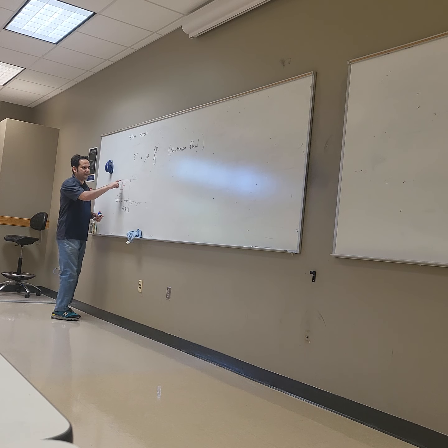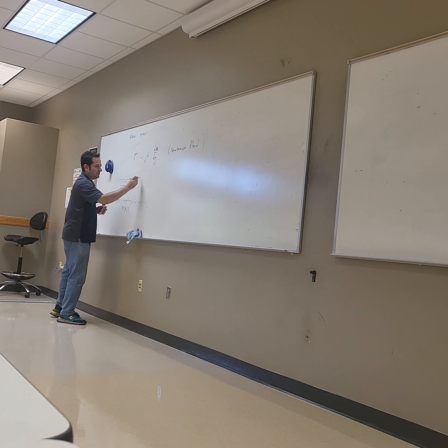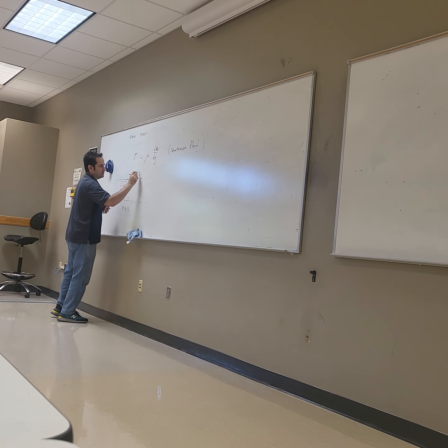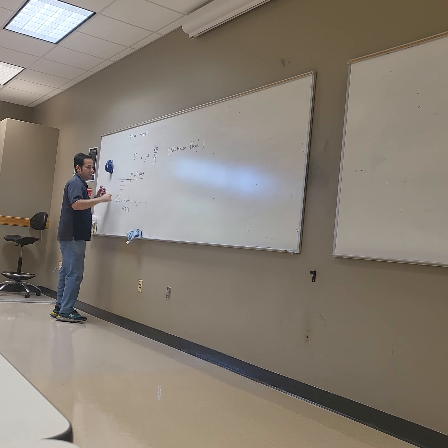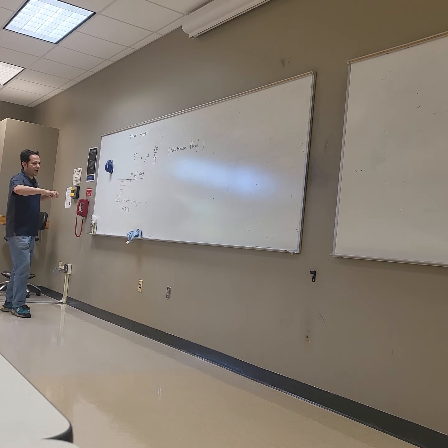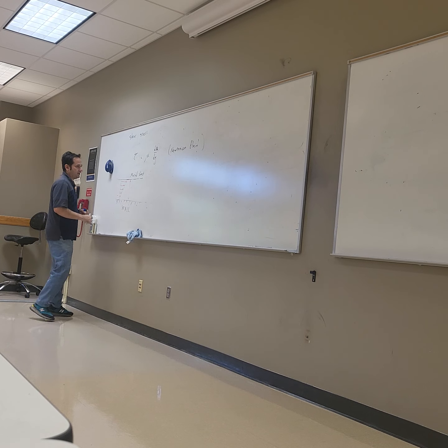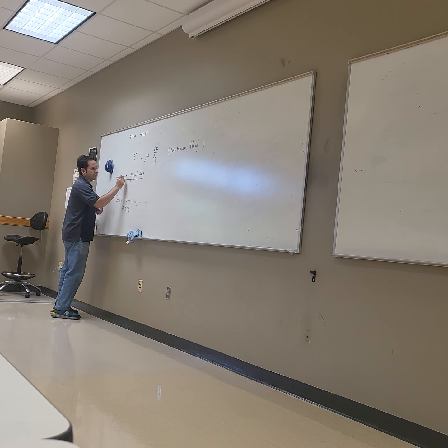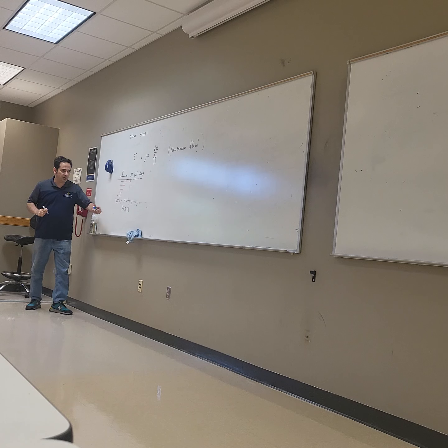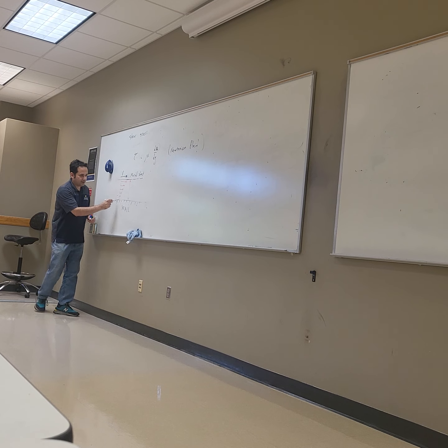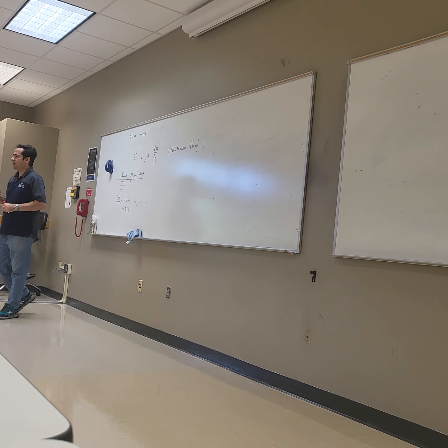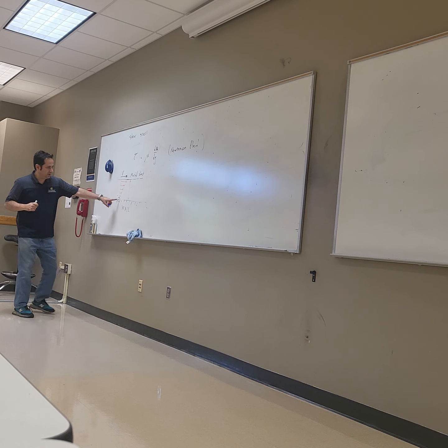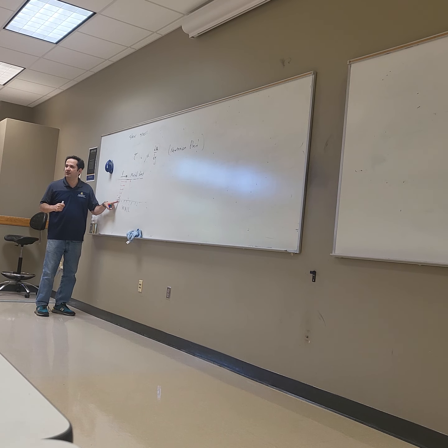And the velocity at the top surface, because I'm moving this top surface with my hand, let's say this is a metal sheet, and I use either a roller or my hand to push it to the right. So let's say this top sheet is moving with velocity v, but at the wall it is 0. If I have a microscope that I can zoom infinitely on this, what's the velocity here? Always 0. So the velocity here, let's call it u.